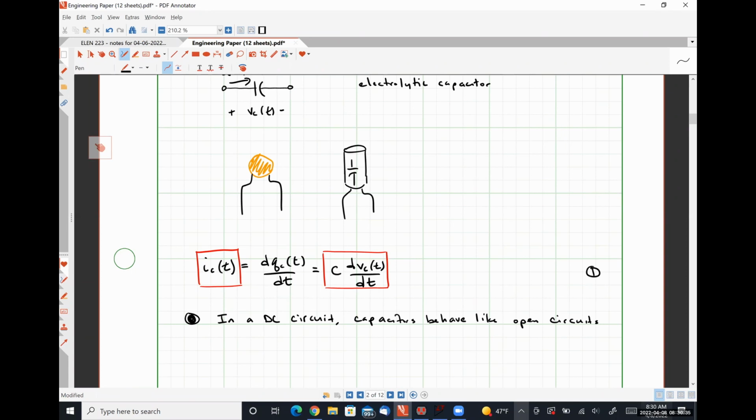Without doing too much derivation here, what would we expect to happen if the voltage across a capacitor changed abruptly, changing instantaneously from, let's say, 0 volts to 1 volt? What would the current have to be? Infinitely large. Can you create an infinitely large current? Of course not, because that would mean creating charge out of nothing, violating the law of conservation of charge.